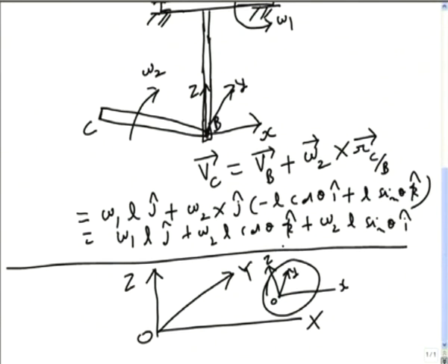Now this axis system is also attached, but this time it is not parallel, instead it is rotating also. So suppose x, y, z rotates with angular velocity big omega, that means the rotation of the axis is by big omega, which is different from the angular velocity small omega of the body.